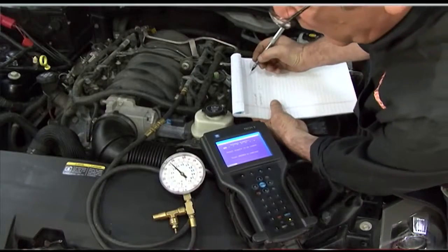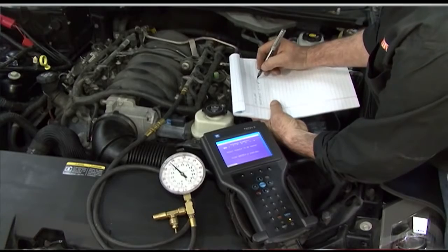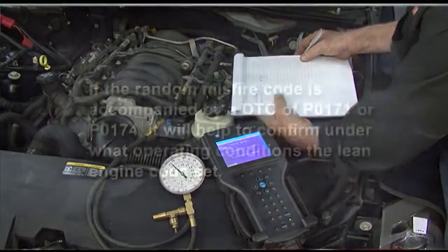A good diagnostic routine requires attention to every detail. Solving a misfire that is evident right now because of a vacuum leak, but missing that the powertrain control module actually coded for a misfire that was occurring on the highway, could lead to a disappointed customer.